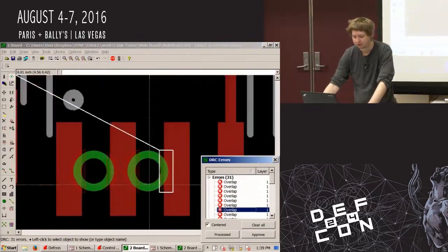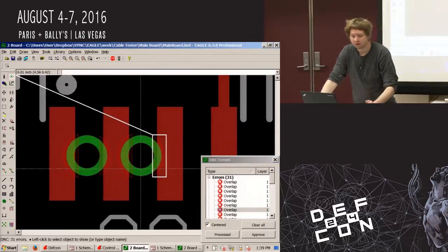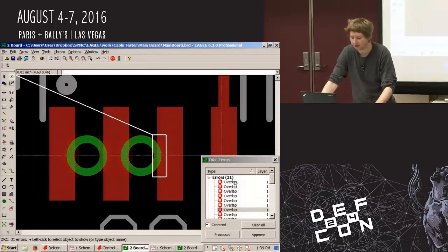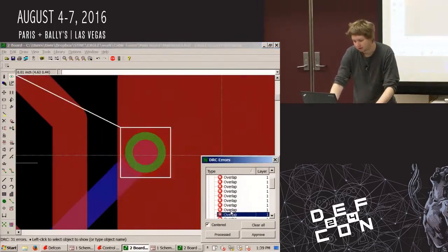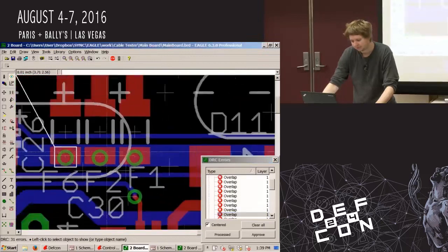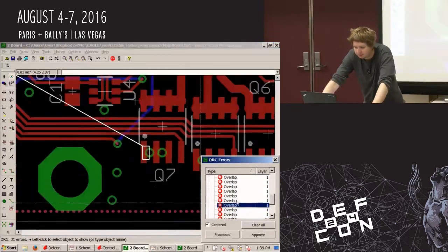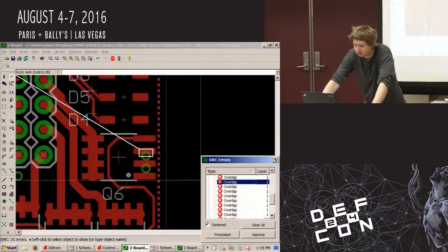Now here, you do need to be careful. If you're not doing all this stuff by hand, you can't really get away with this because the via will actually suck away all the solder from these pads. Yeah, more tomfoolery, but this board definitely got the job done.